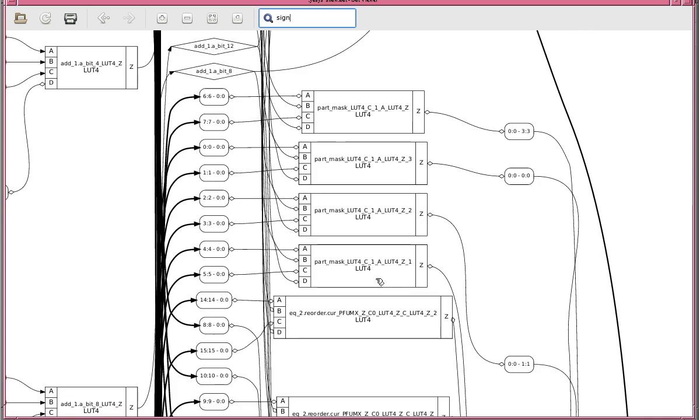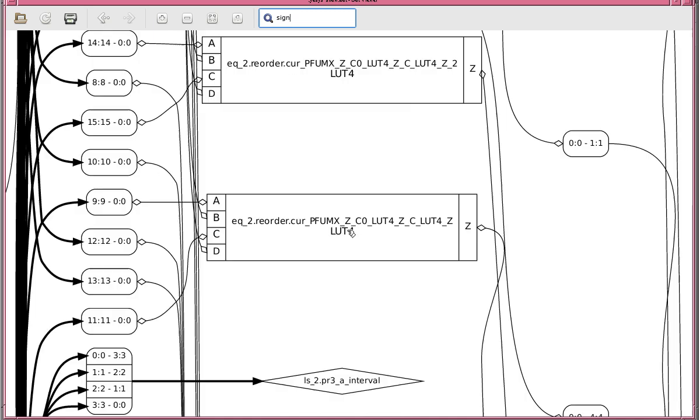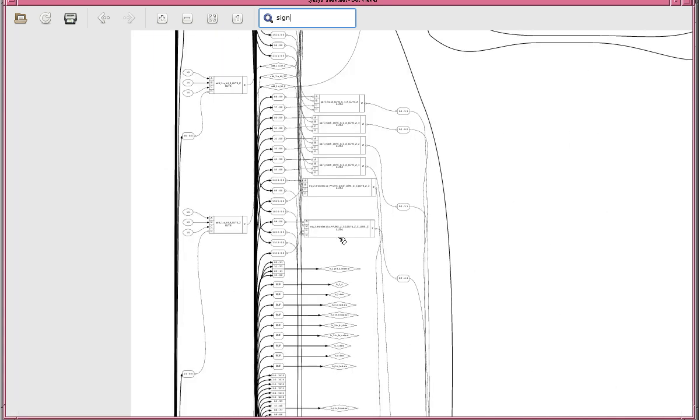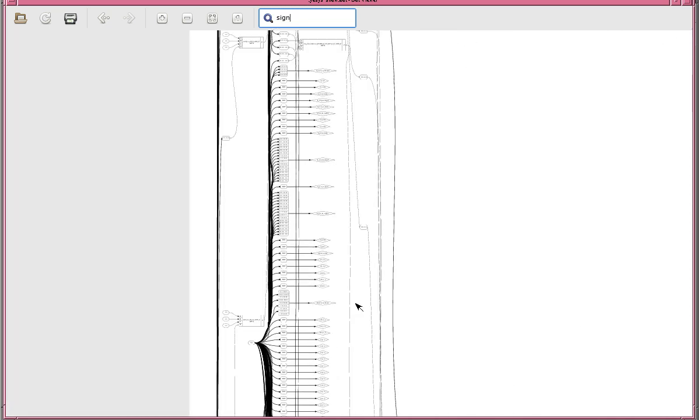All right, okay. So it's turned it into a series of resources, because Yosys contains an understanding built into the actual source code of the Lattice ECP5 cells, which we described on the previous diagrams: LUT4s, BRAMs, PLLs, MUX, DSP, multiplier slices, etc. So that's what you end up with there.